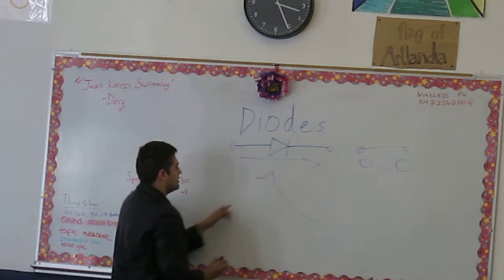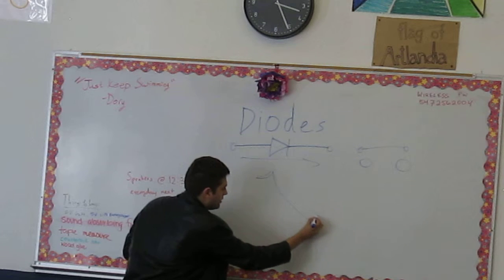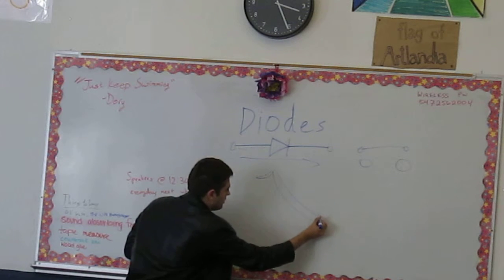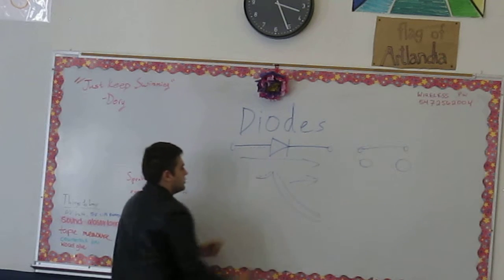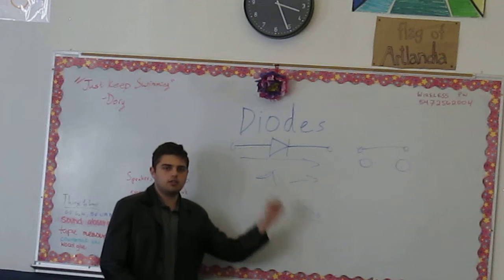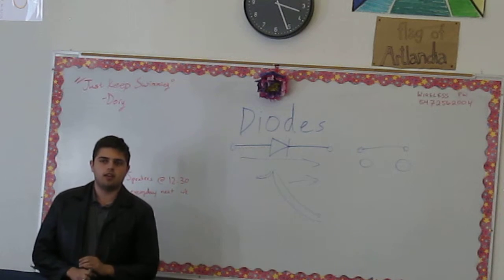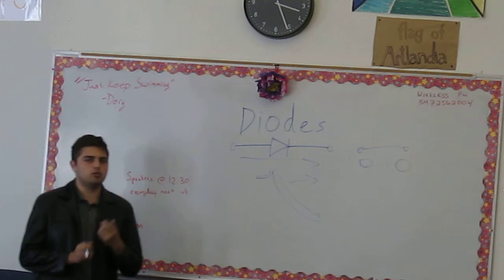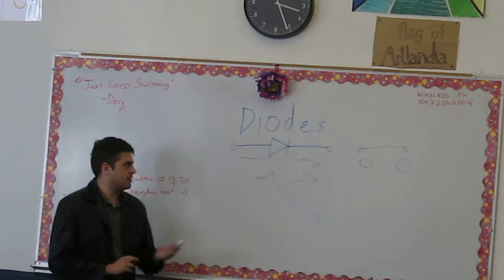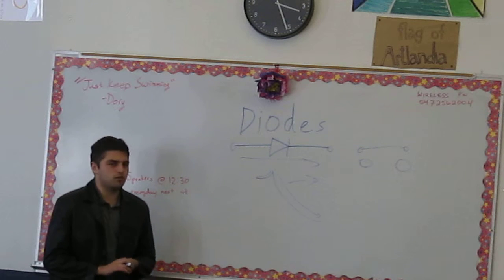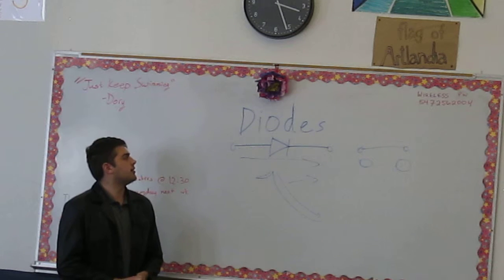So you've got these electrons. They got excited enough to get over this first hump. Now, when one electron is falling down here and it's using all this energy, each electron emits a photon. So for each electron that's falling down this thing and losing all this energy, passing over this diode, you've got a photon for each one. And if you've got luminescent materials like, I can't remember the names, I think it's gallium arsenide or something like that, then it's dissipated in the form of light. So then you've got each one dissipating light, and that's how you form an LED.